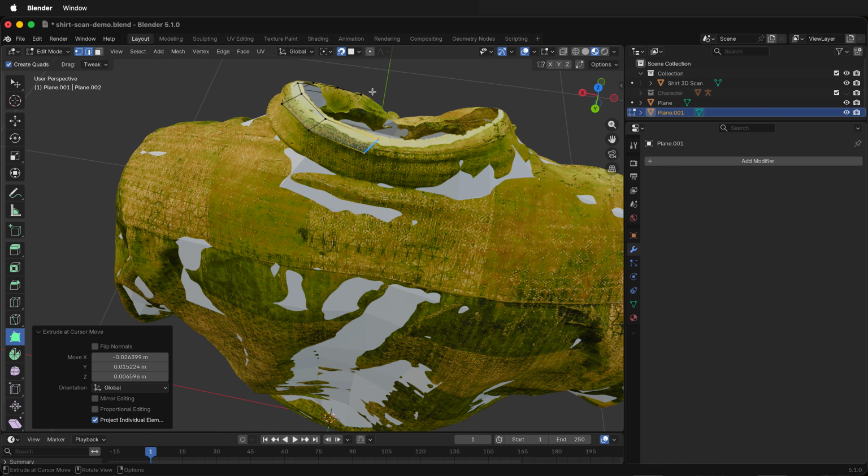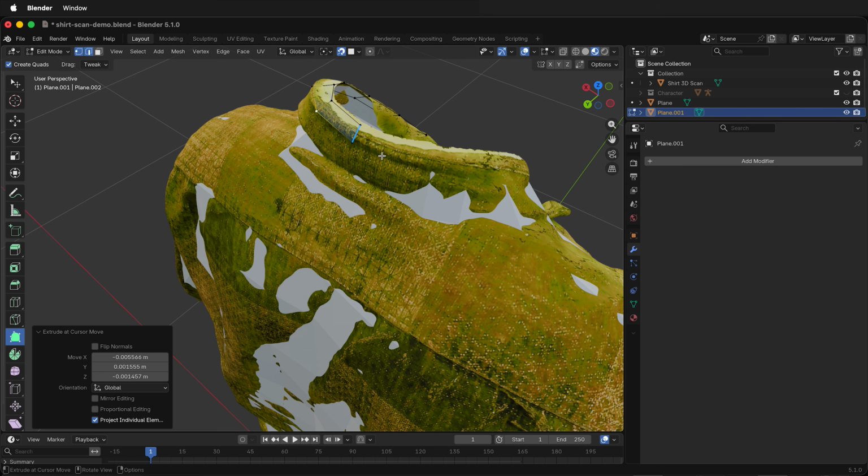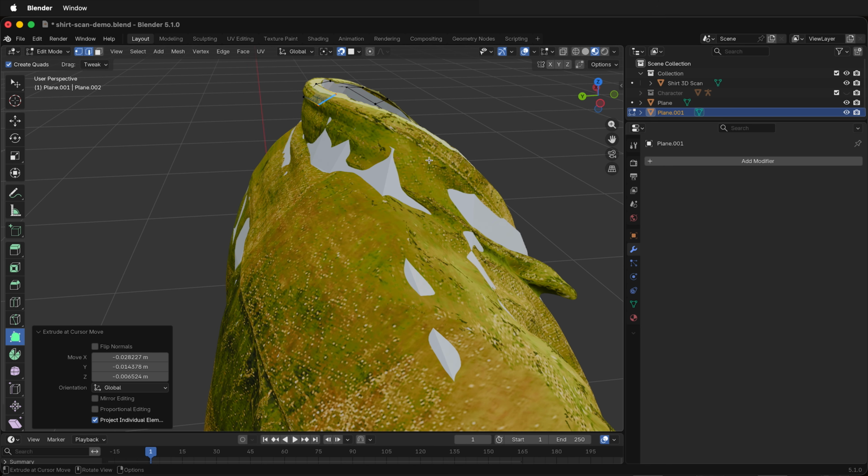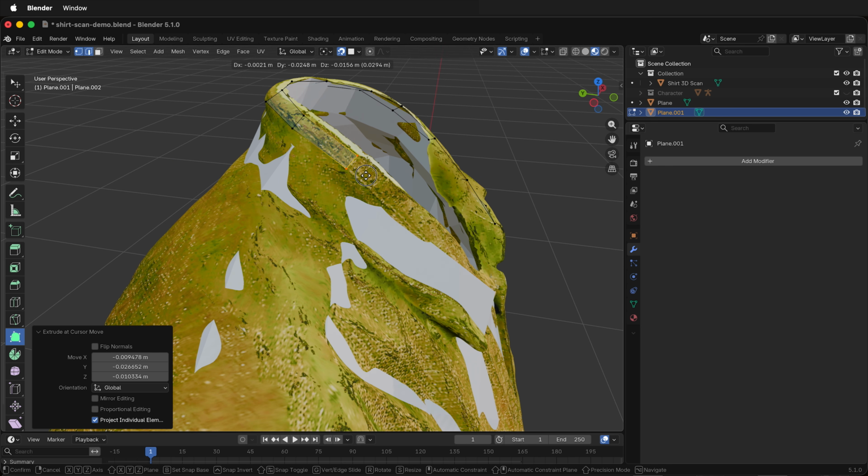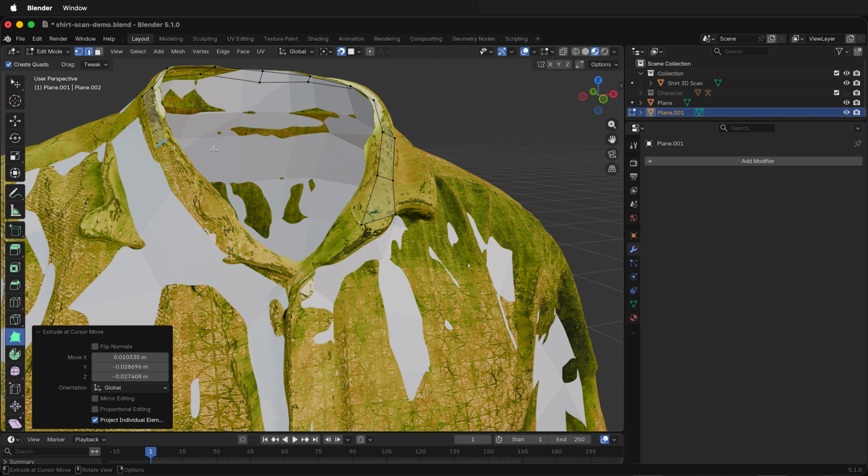Eventually, all the edge loop counts need to match up, but you can always add or subtract as needed. So don't be too self-conscious. Put the edge loops where you think you need them to hold the detail, with the goal of generally using as few as possible until you definitely need more edge loops.